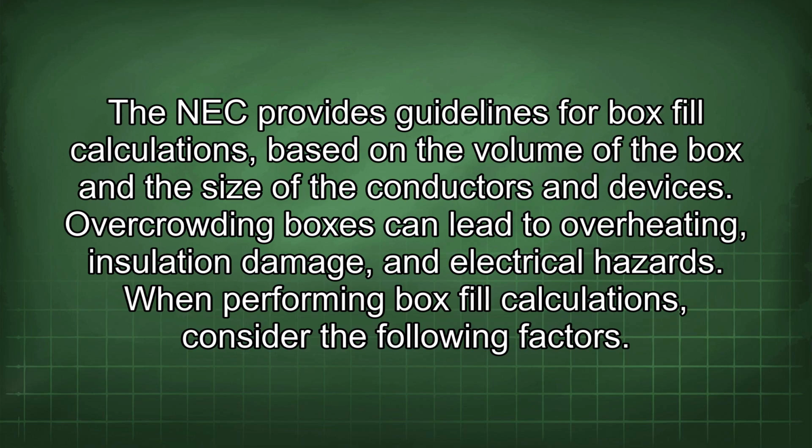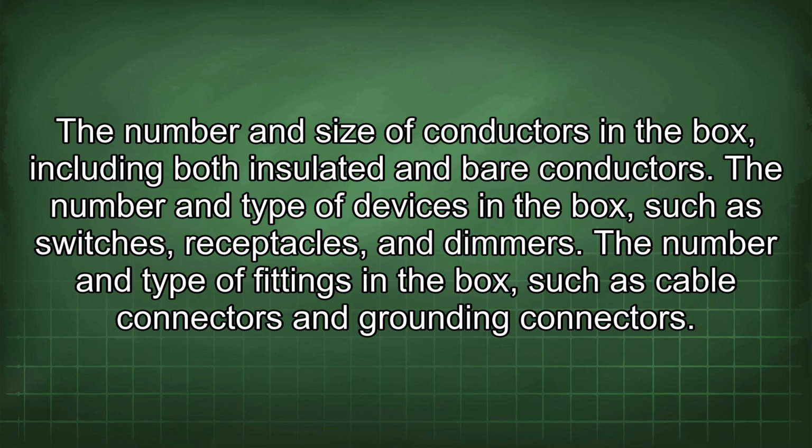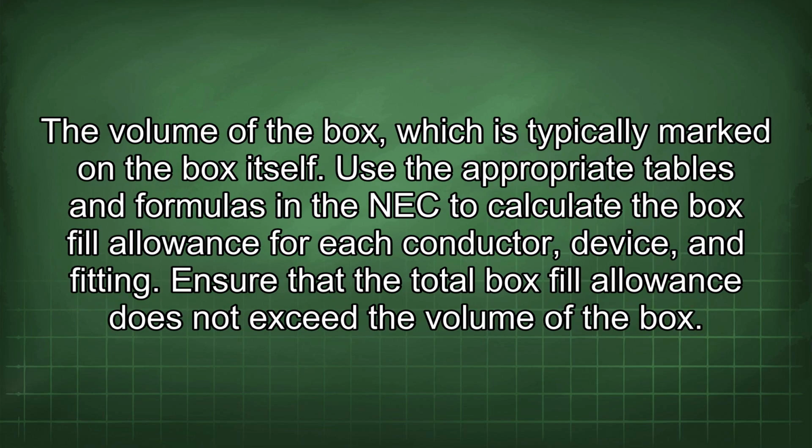When performing box fill calculations, consider the following factors: the number and size of conductors in the box, including both insulated and bare conductors; the number and type of devices in the box, such as switches, receptacles, and dimmers; the number and type of fittings in the box, such as cable connectors and grounding connectors; the volume of the box, which is typically marked on the box itself.